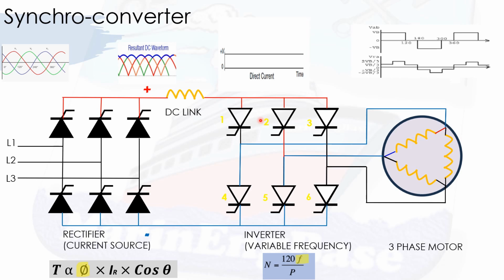In that situation, you have to control the rectifier bridge and cut off the DC supply to a zero value. Then the thyristors in the inverter bridge will come to the off state. And if you want to fire again, you have to switch the power on again using the rectifier bridge. So this is how it operates under low voltage or low load situations. Let's say your main engine or main propulsion uses a VFD motor, then at 10% load or below, you have to use the rectifier bridge, the controlled rectifier source, to have zero output. Then your inverter bridge can get into the off state.